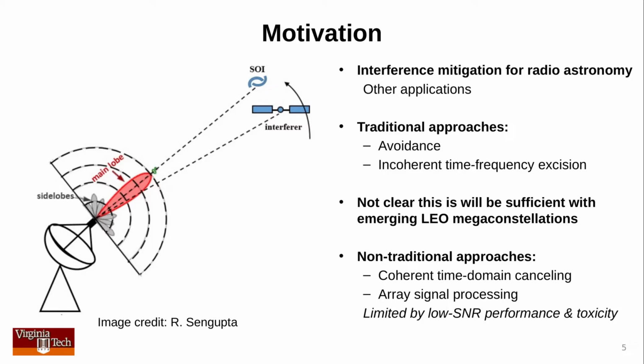The key idea is that because reflectors tend to be large, and therefore the beam is very narrow, the satellite signal is usually incident from the side lobes. So, let's see if there's something we can do to move side lobes into a pattern that puts the satellite downlink into a null.